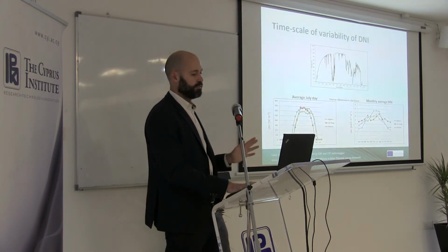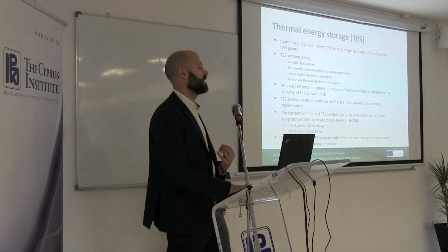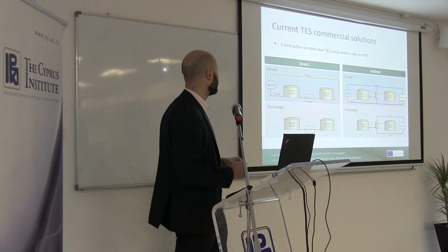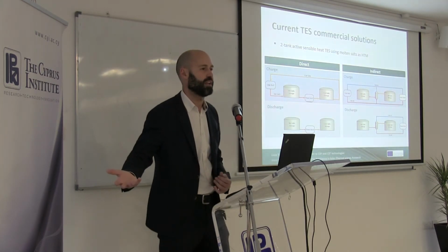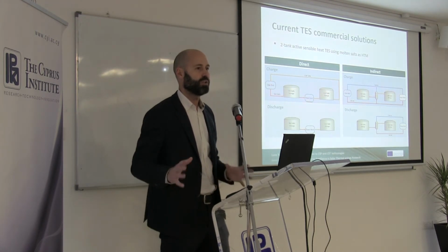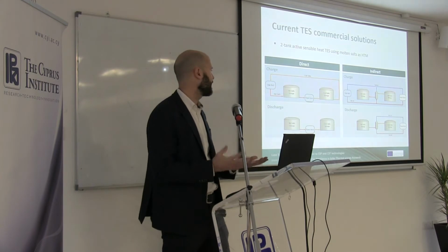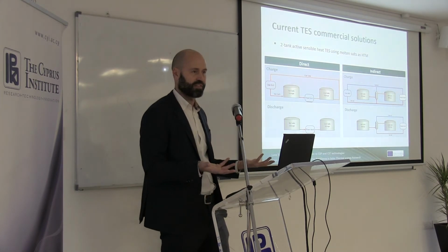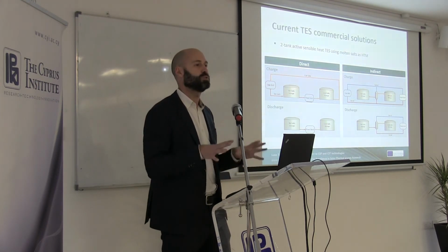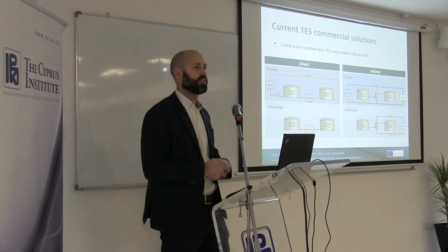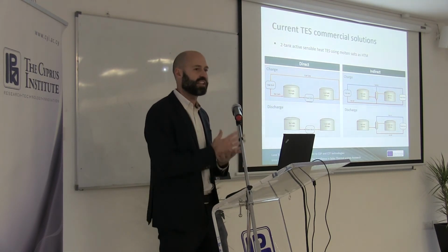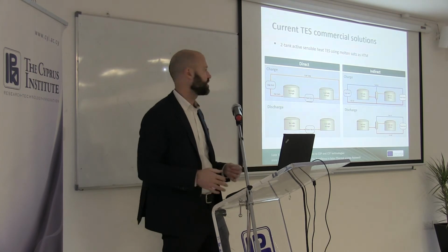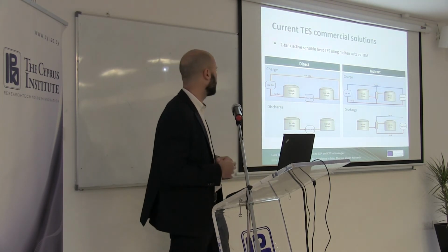And finally, just one word, the important feature is thermal energy storage. The concept today is very simple, I would say. When we have excess solar heat from the solar field, we just store this heat as sensible heat by heating up a liquid, molten salt in commercial plants. This is the only commercial solution for thermal storage today, even if we will see on Thursday, research in this field is very active. This is now one of the most active fields of research in concentrated solar thermal systems, because it's very important to reduce also the cost of this part of the plant.